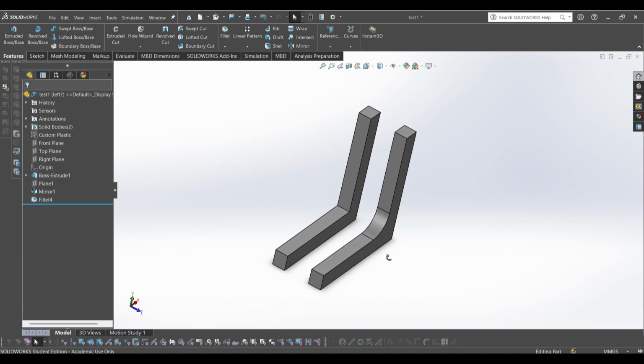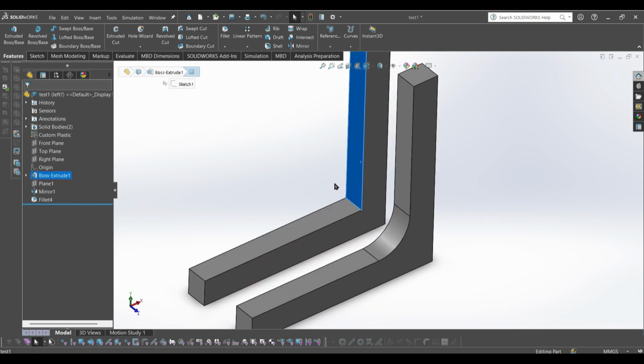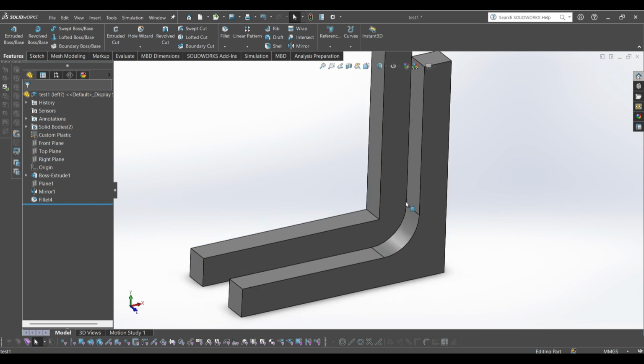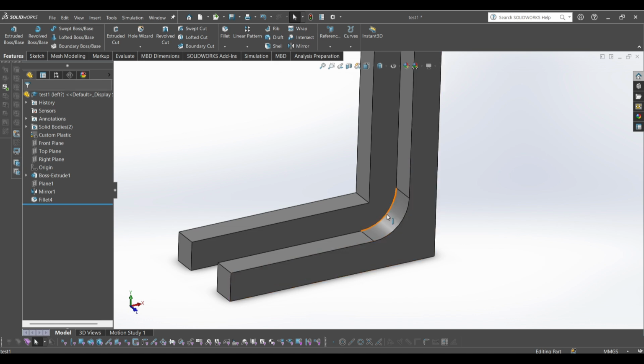And the reason that is, is because if I held this side of this L piece and this side of this L piece with two different hands and tried to snap it apart, it would break really easily because this edge is super sharp. But if I tried to do the same thing with this one, it wouldn't be as easy because this edge is curved. And you can think of it as sort of fusing these two faces together when you add a fillet here. And it can either be a fillet or a chamfer, it doesn't really matter. It still makes the part stronger when it gets 3D printed.